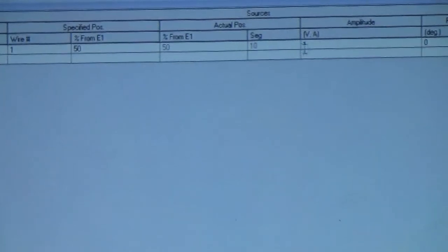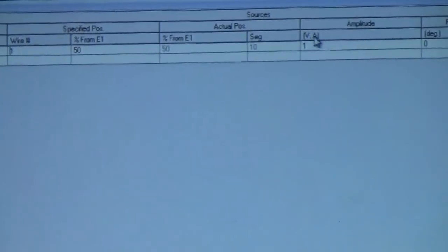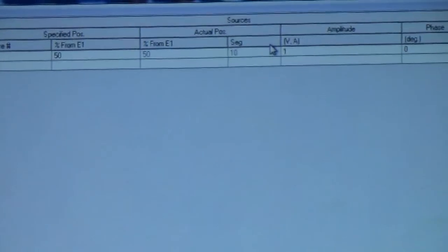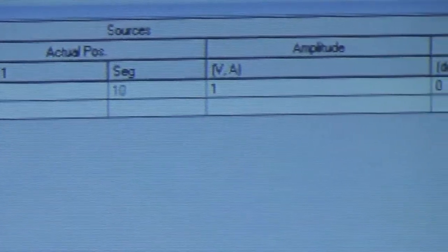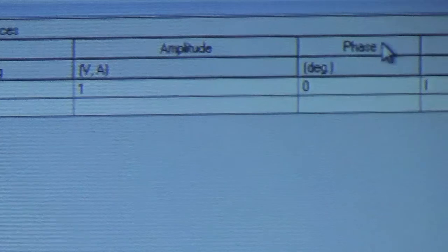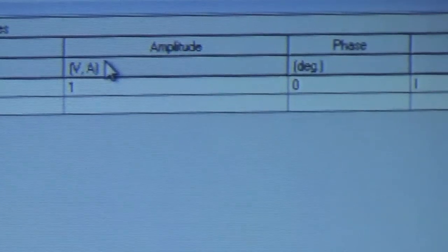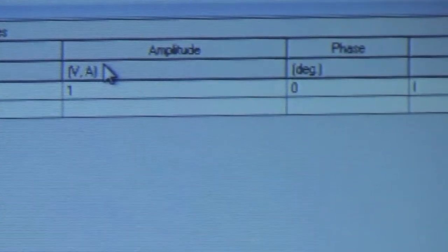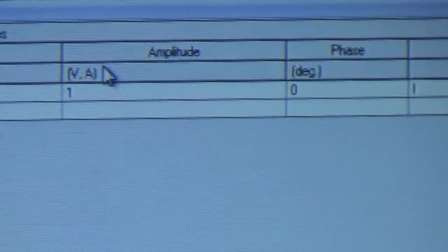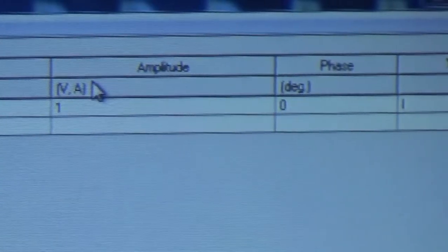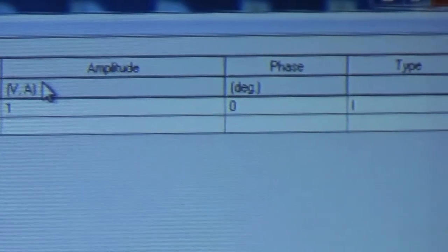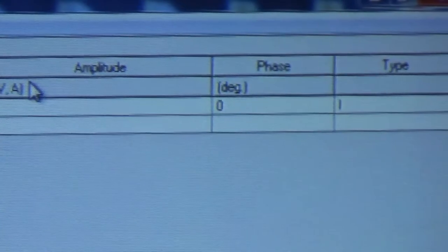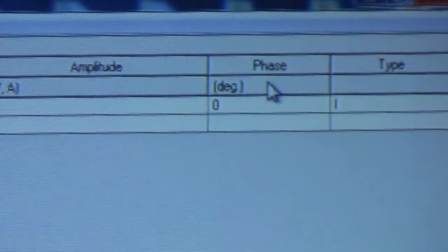The type of source, there's voltage sources, there's current sources. Typically, you stay with a current source, because that's what a center fed dipole will use. There's different reasons that you would use the voltage, or there's split feeds if you have 2 segments that come together at a 90-degree angle, things like that. And like I said, this thing can do a lot, but just for doing the basics is what I'm going to show you tonight.